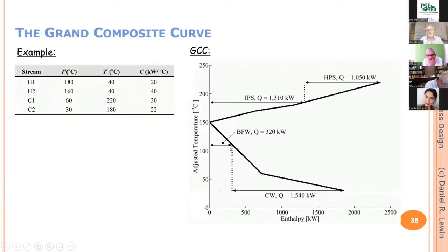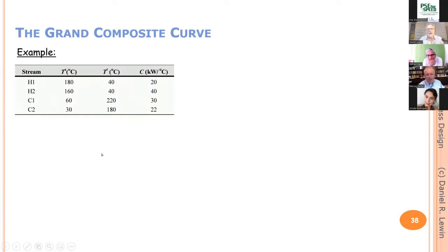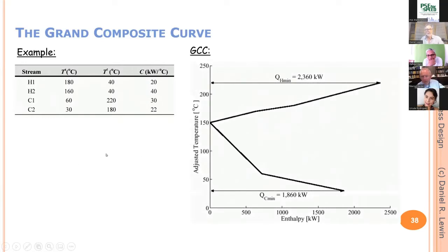Grand composite curve, well, the idea is nothing really specially new. Basically, we actually had the data for grand composite curves once we do targeting. All we're doing here is plotting the residuals on the x-axis against temperature intervals on the y-axis. That information we already had.